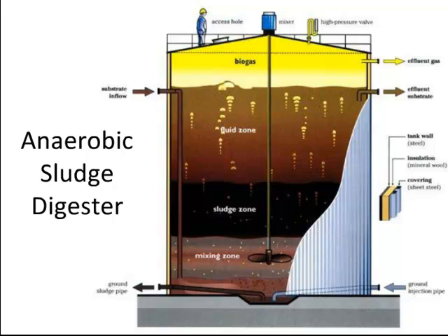If you have to use it without a drying bed, then you're going to have to disinfect the sludge as well, using some type of gas like chlorine, or utilizing electric ultraviolet light.